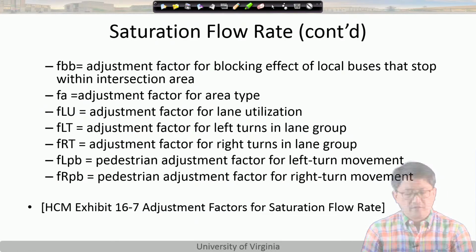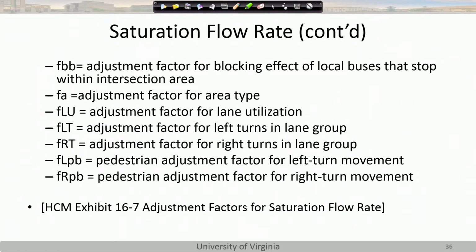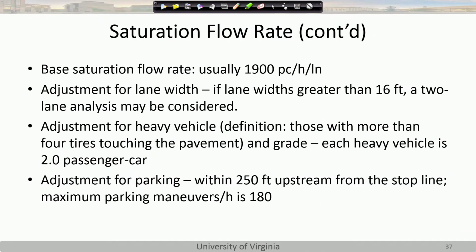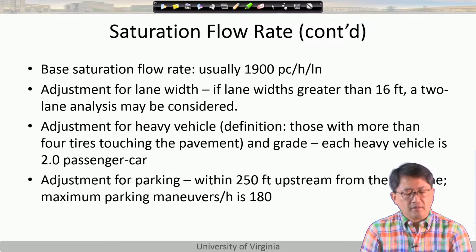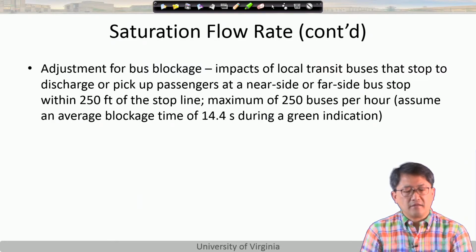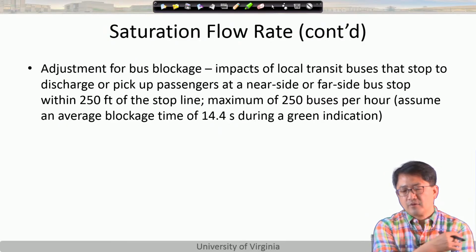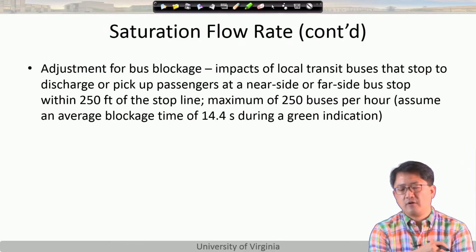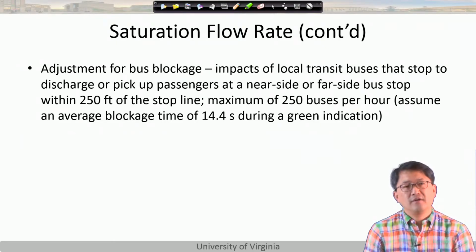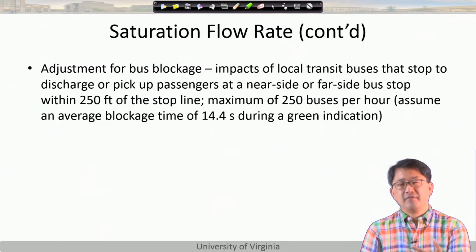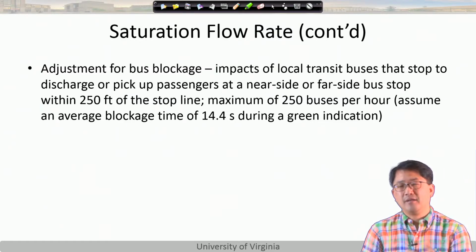All these are the factors, and it's available in the HCM. I'm sure it's the same thing as in your Indo HCM as well. Sometimes people use the 1900 as well. Adjustment for these and others are commonly done. Parking is affecting as well. Bus blockage is another challenging issue. Bus often blocks vehicles. So that's why Professor Goswami actually mentioned a near side bus or a far side bus stop. So people favor having a far side bus stop because of that issue. If you have a near side bus, even though you see the green and the bus is stopping, you cannot actually move.